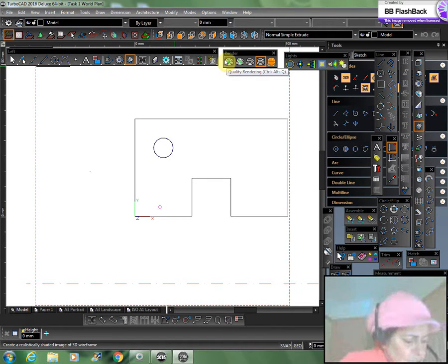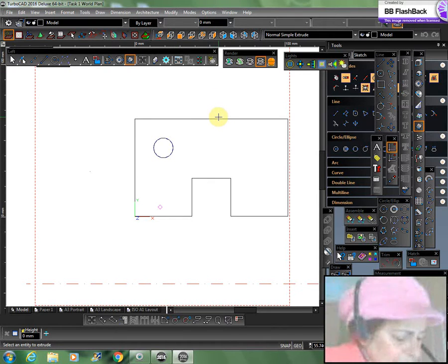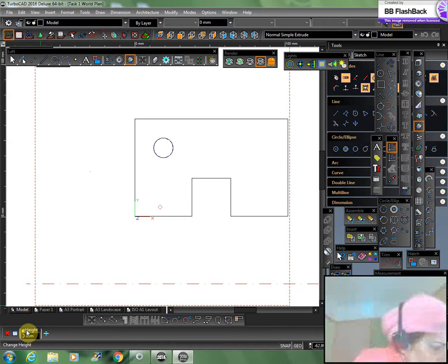this extrusion tool sweeps a 2D profile in a plane perpendicular to the work plane. To create a 3D object, select the simple extrude tool and select a profile. Then you click on the profile. Use the keyboard to access the height. Here is written height. You type 20.